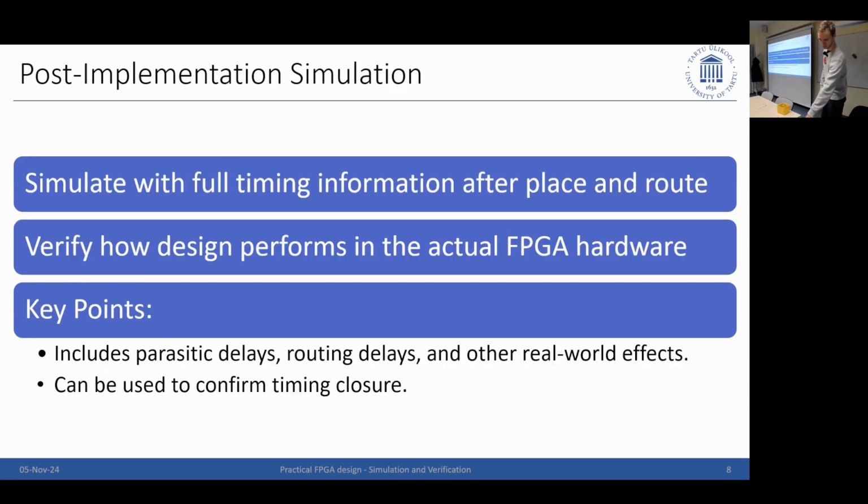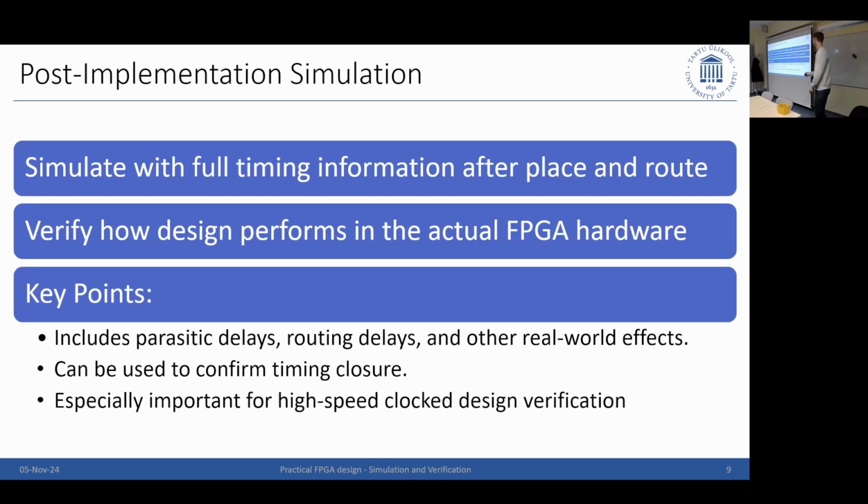Okay, interesting. I forgot one point here. The other part is that you basically do this mostly for high-speed clock designs. There's a way that you can allow a propagation to take multiple clock cycles. What a timing report does is check if I match the timing constraints.